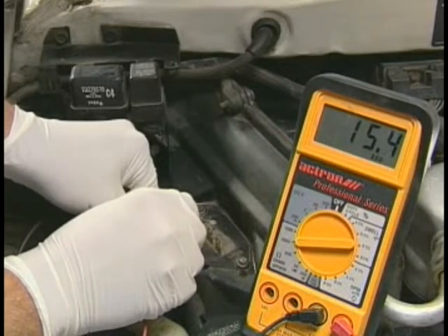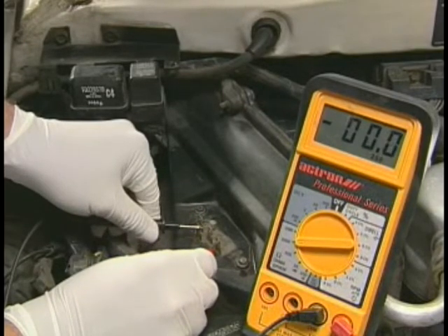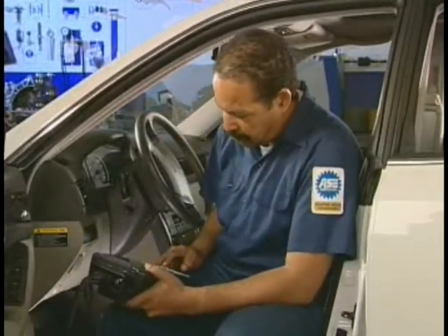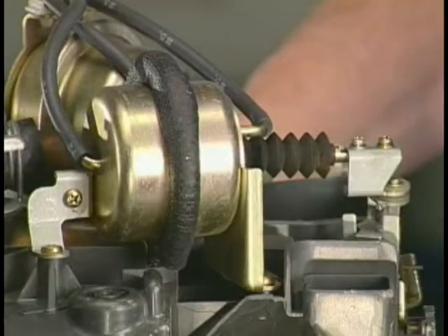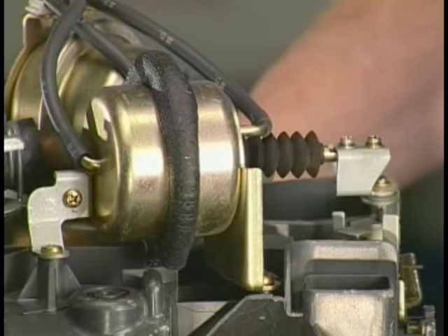Relays should be checked for current using a voltmeter and for continuity of the coil side and ground side using an ohm meter. You can check the input sensors and output signals on engine control units and body control units using a scan tool. The most common cause of failures in the air and vacuum control systems is leaking hoses and diaphragms.